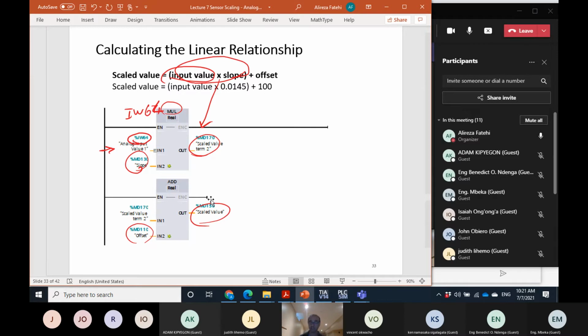There's another method to implement it, or let's say there's another instruction in the Siemens PLC. This is special for Siemens PLC, that you can use to implement a more complex formula. I don't want to say very complex, but anyway more complex, not that simple. You see that to implement that with the basic instructions, we should implement it part by part.